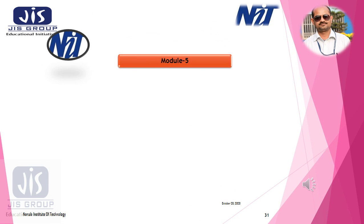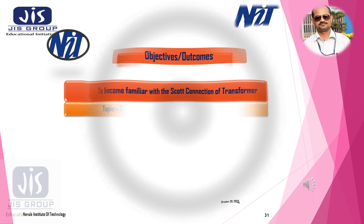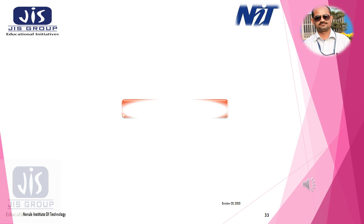Okay, so in module number 5, we are going to discuss the second part of Scott connection of three-phase transformer. Previously, we have determined the voltage ratio relationship, phasor diagram, and the position of neutral point N. Today, in lecture number 5, we are going to discuss the relationship between input and output current.